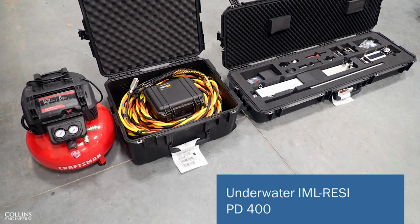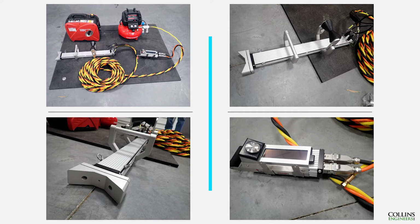So there's also an underwater unit too. It's actually an electric drill, just like the above water unit, but it uses compressed air to keep the internals dry. So we have one of those too. This is what it looks like when it's all assembled. You got a generator, you got your low pressure compressor, there's the hand unit that the diver holds, and then there's the topside unit that controls it, so they just separate that out. And then it has a different nose piece on it that you can use to stabilize the drill on piles. So that was kind of a new development from IML. It still runs on batteries though, it's not pneumatic. But you can use it above water and underwater, so you don't have to switch drills or anything like that.